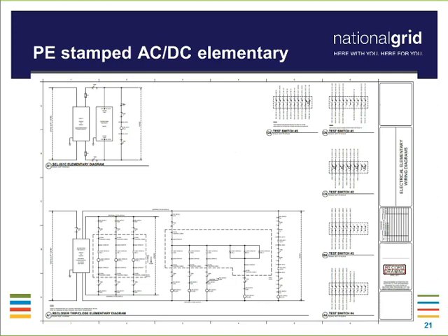And it also shows the test switches associated with it, which would be, I would want to say, necessary, very fundamental to providing a proper witness test plan. Having the test switches to be able to isolate units so we can test their functionality in the field, if there's troubleshooting needed on the device. So all that information gets displayed on a proper AC or DC elementary.